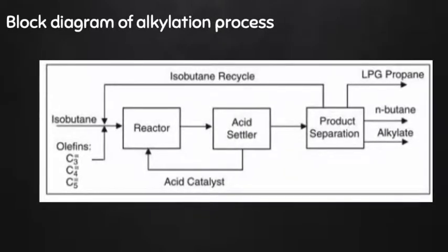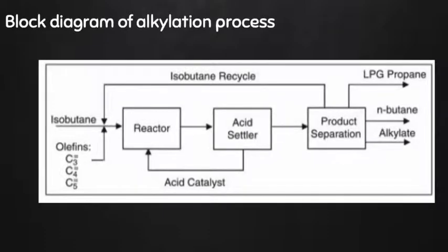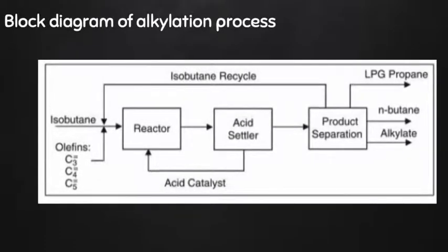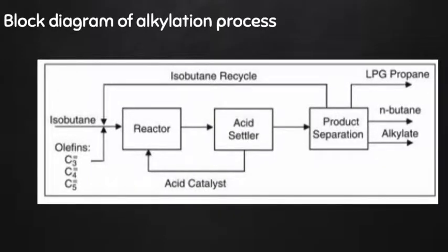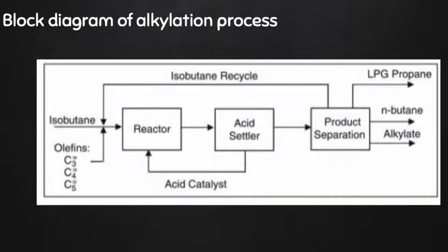Also, some form of heat removal is essential because the heat of reaction is approximately 14 times 10 to the fifth power joules per kilogram, or 600 BTU per pound. Therefore, the overall process is a composite of complex reactions, and consequently rigorous control is required of operating conditions and of catalysts to assure predictable results.